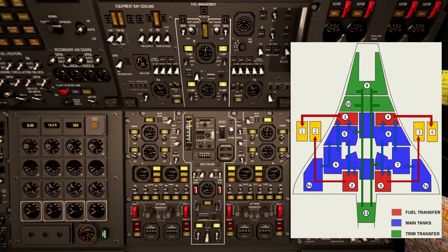Just to remind you, we have different tanks in Concorde, and they are represented here on this panel. You see the number, we have tank number 9 and 10, the two trim tanks in the front up here. We have input valves, so if ever we need to put fuel back in these tanks, we're going to turn these valves on, they open up, and now if ever we would turn the pump on in tank 11, which is down here,